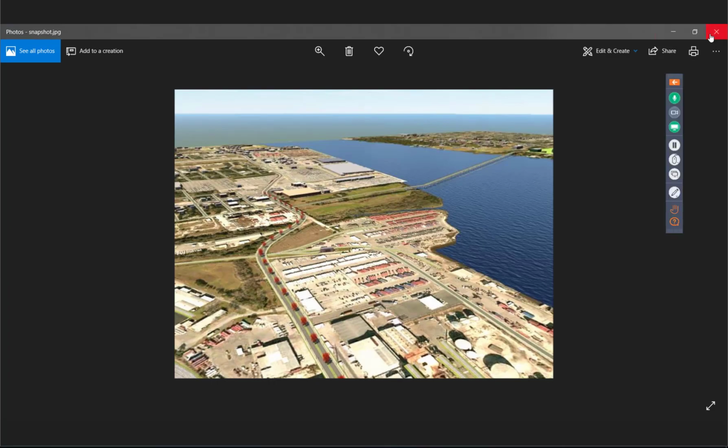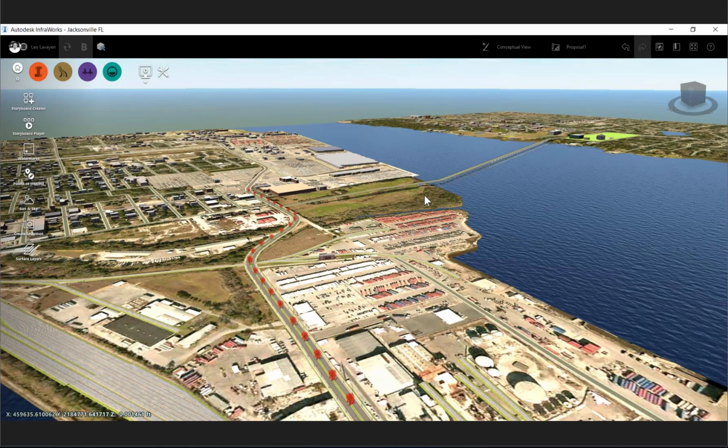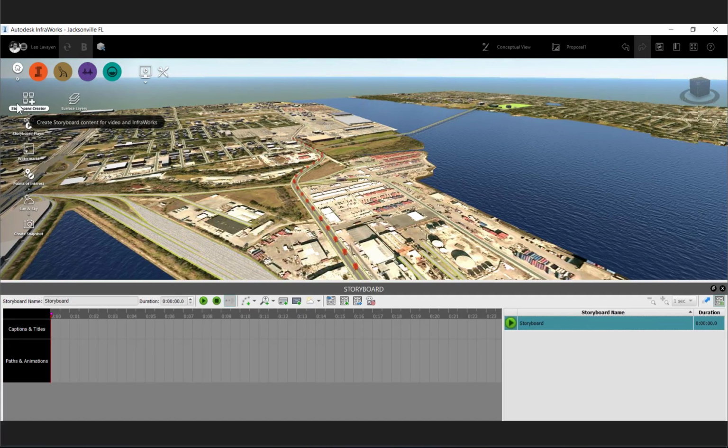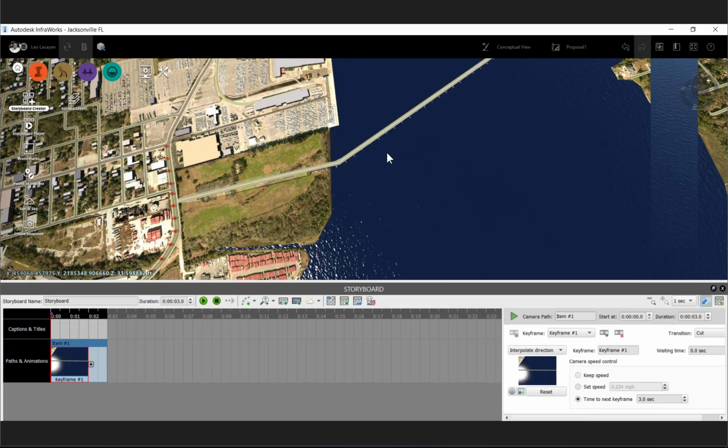What I can also do, which I enjoy a lot, is creating animations. And having worked from AutoCAD to now working inside of InfraWorks, they're called storyboards. What I do inside of InfraWorks is create snapshots, just position my camera, or my view in this case, and pop a view. It's referred to as a keyframe. And then I'm going to do this really quickly and dirty inside of here and get another view and choose to pop another keyframe and choose to zoom in or pan out.